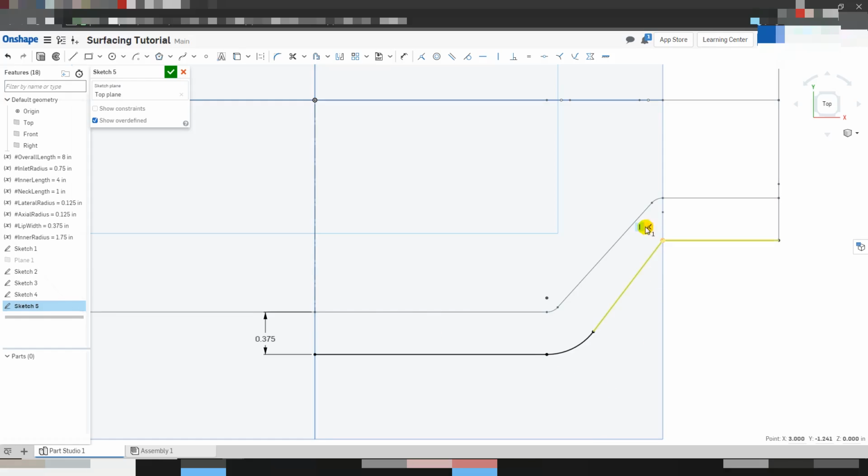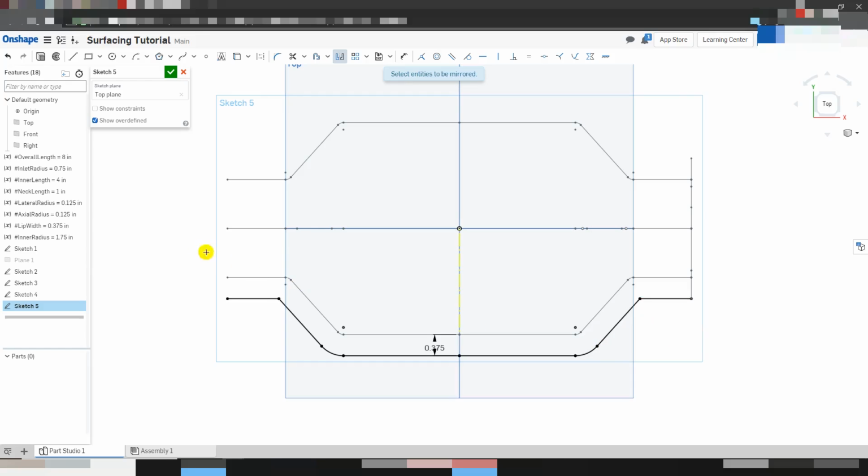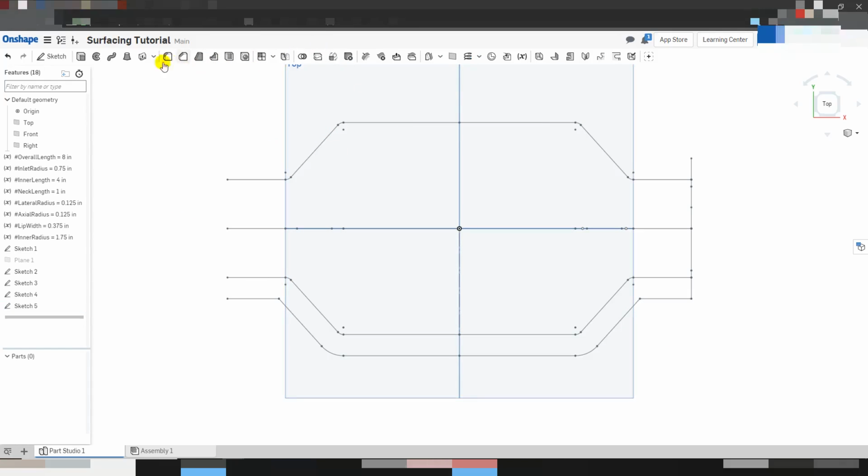And it looks like I don't actually want to be vertical here. So we'll go parallel. It is a high priority to maintain this lip width, so I have the same width here, here, and here. If I do not, it may be difficult to weld the clamshell from a design perspective. Now, I'll make a mirror, choose this line, here, here, here, here. And we're done with that sketch. I'll simply make a mirror image of that sketch.